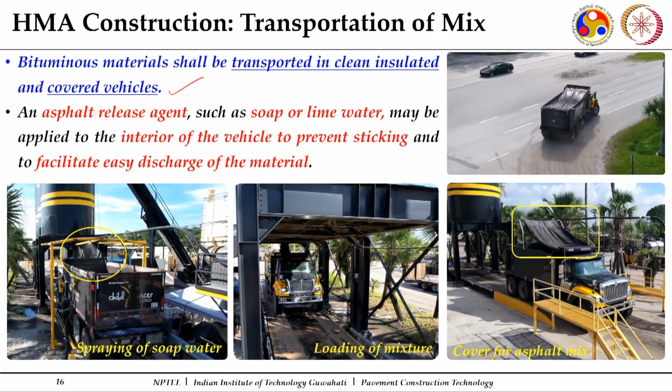While transferring it, you may have to clean up. The mix should not get stuck to the body of these tippers. So we usually use a release agent, so that when it goes to the site and is emptied in the paver, the complete mix goes out. It should not remain stuck to the surface of the tippers. Release agents such as soap or lime water may be added to the interior of the vehicle to prevent sticking and to facilitate easy discharge of the material.